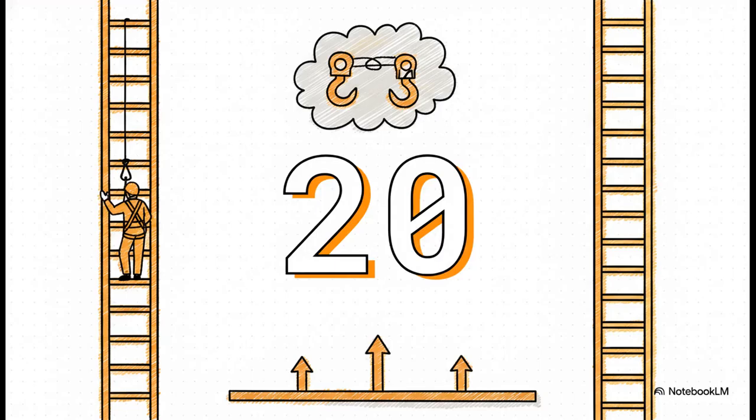But 6 feet isn't our only trigger here. We also have to talk about 20 feet. That's the specific height threshold that demands specialized fall protection when you're using fixed ladders. If a fixed ladder on our site climbs higher than 20 feet, just doing a standard climb is not going to cut it anymore. You have to be actively tied into a safety system.